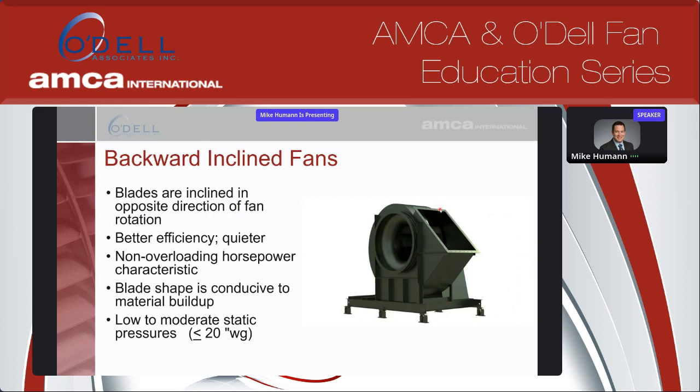That takes us back into the backward incline fans. So you can see here you have a large inlet and a large outlet. These fans move higher volumes, lower pressures. They tend to have higher efficiencies, up to, depending on the wheel, 70, 80, even 85% efficiency.